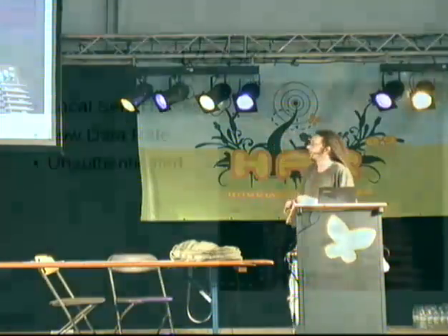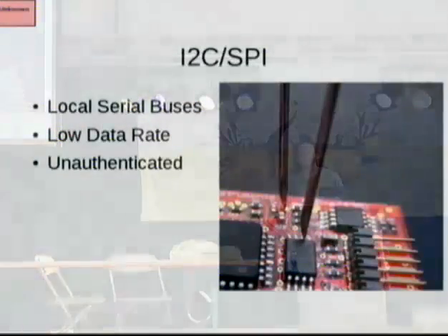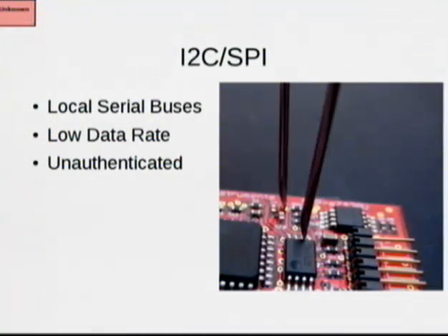And then once you've identified which pins and which rate and which protocol you want to use, you can stick hypodermic syringes into the board. These very quickly create a clean electrical signal with no soldering. Very few remaining marks will be on the device. This is a memory chip here underneath the laser. And then over to the left, this larger chip is a microcontroller.